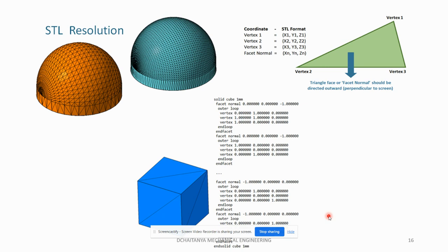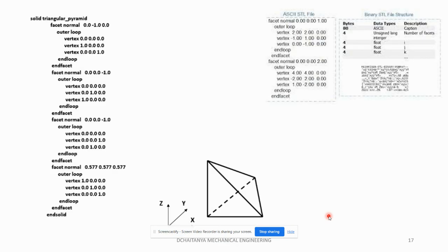This is the format of this particular STL file, where you can see the back end. Each and every node will be identified, and triangular facets have 3 vertices, and the normal perpendicular to the screen is also another attribute. It may be formed with different coordinates, so you need to examine those coordinates. Then you can change the program and automatically rectify the error.